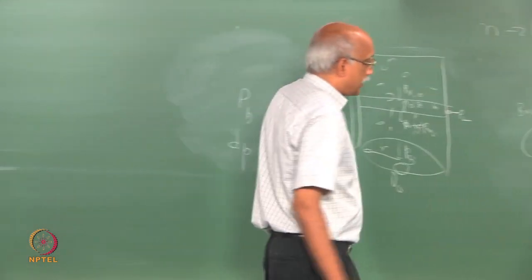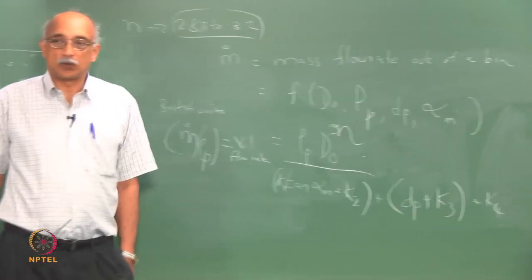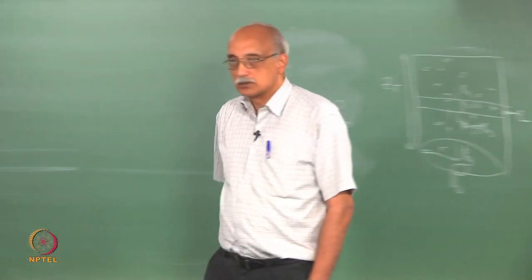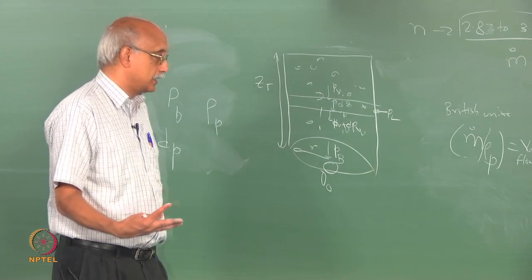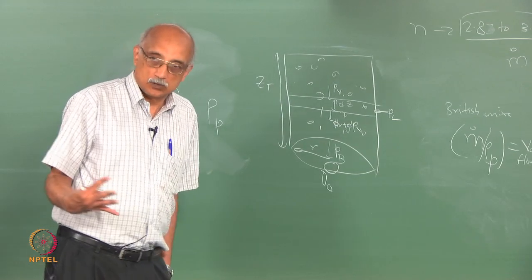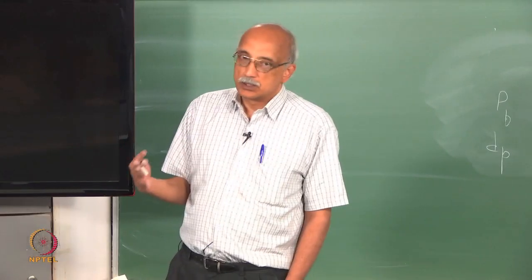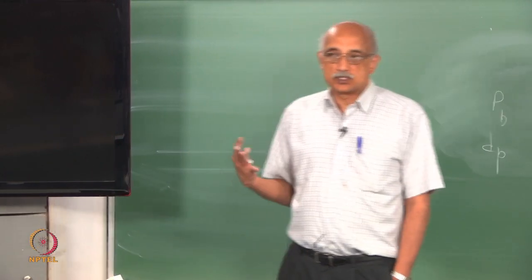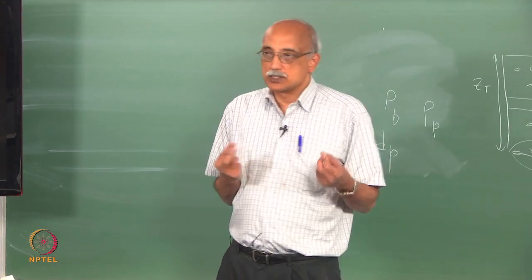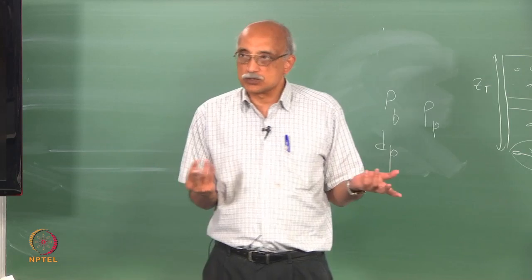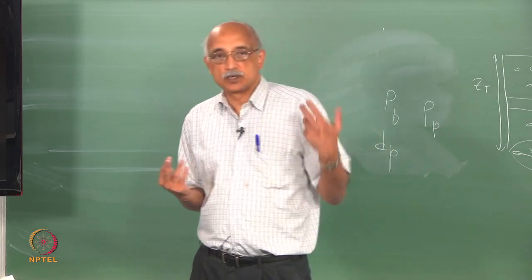It is interesting that in this expression dP is at the bottom, which would seem to indicate that material that is smaller would tend to flow through faster from a circular hole. Is that true in general? No. I mean, if the size reduction leads to cohesive conditions, this is not true, but remember what I said, that this applies only to the flow of granular material.